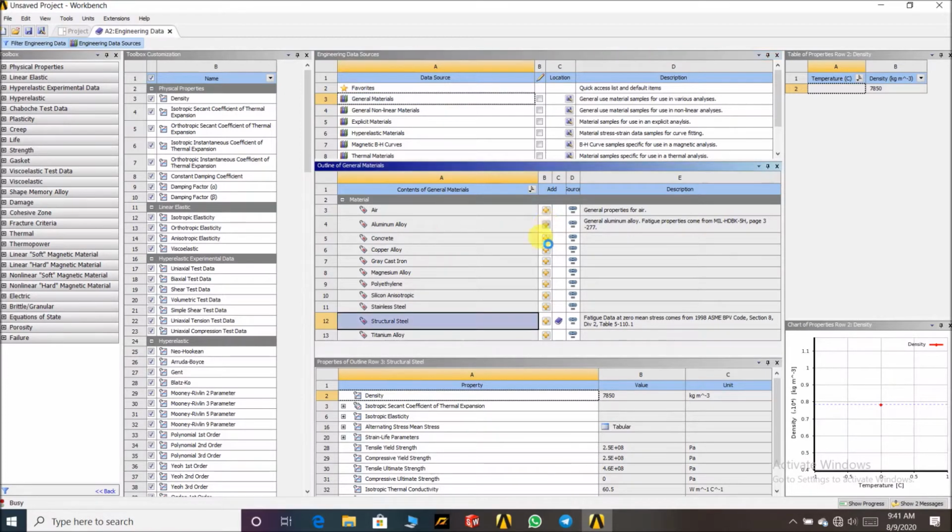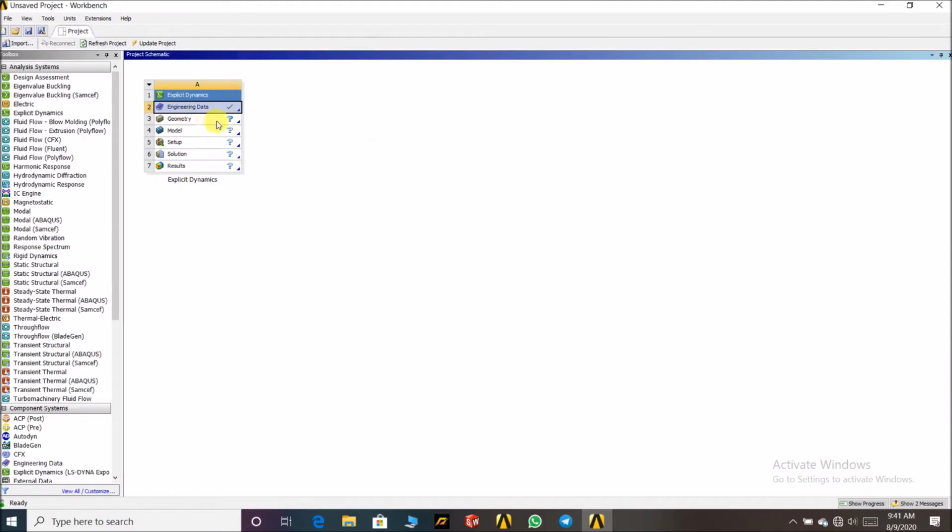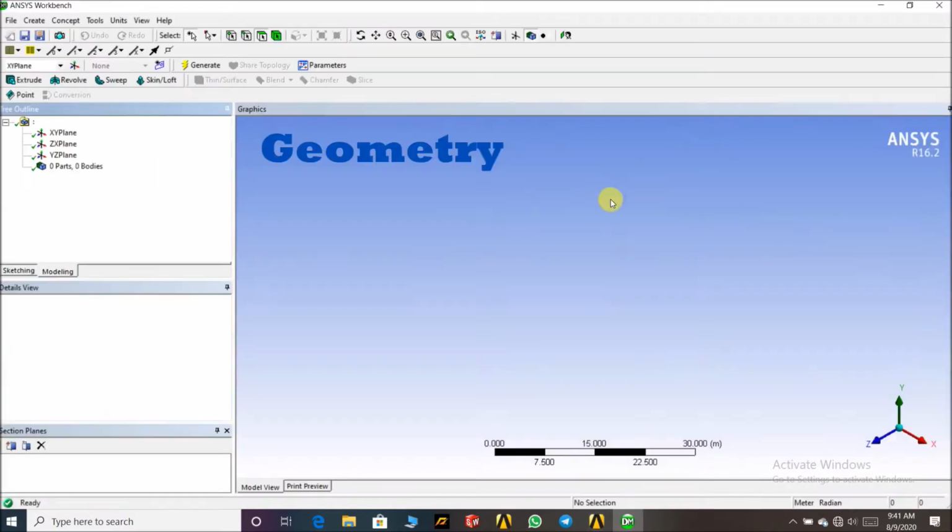We select aluminum and stainless steel for the bullet and polyethylene for the wall and pond. Why did I select the polyethylene? Because polyethylene is a very ductile and soft material, so we can see a better dynamic analysis in the bullet.